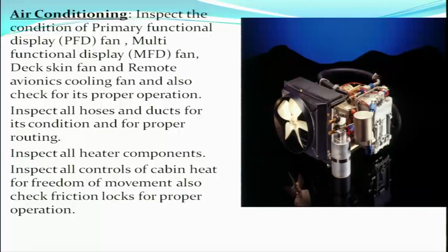Air conditioning: inspect the condition of primary functional display PFD fan, MFD fan, deck skin fan and remote avionics cooling fan, and also check for proper operation. Depending on the aircraft, in some of the aircraft we have the PFD fan, MFD fan, deck skin fan, remote avionics cooling fan, and all these fans are checked for proper operation.